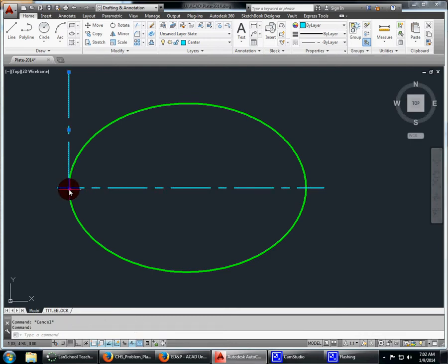There we go. Those are called your node editors, and I simply use them to get them going. And now if I'm having problems with it being nice and straight, if I turn on that lovely little ortho mode, it'll turn it where it's perfectly straight. Hit escape to deselect. Okay, now we want to offset.